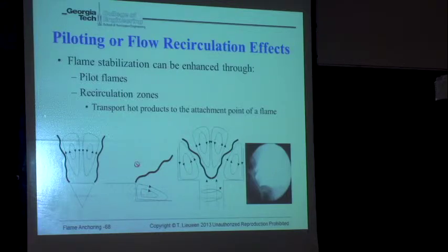And also, that point that I made earlier about extinction is there's always a little bit of a dead space, right? The flame is a few millimeters away, and so there's a little bit of contact. You know, some hot products are coming back here. And so just what the composition is and what the temperature is at this point is an interesting question.